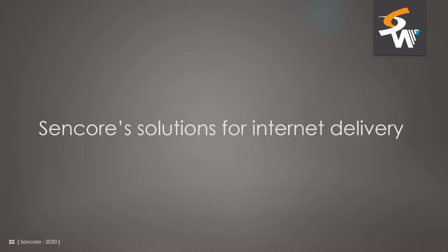Yeah, so the SCP is meant to only be on the front end. So an encoder or transcoder receives all your signals on the front end and then sends them back to the head end or something like that, which is going to receive those signals and do the decoding. As far as decoders are concerned, we're going to talk about some of the Sencore products coming up in the next few slides, both decoders and gateway products that could receive these internet transport protocols and either turn them back into a traditional transport stream or decode them directly. So I'll save part of that question for these next slides, and then if there's additional details I can add after that.